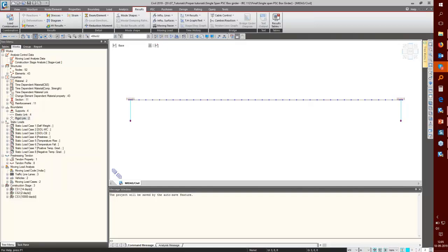Now the solution for this is, first we model a dummy model, or else we model the same thing without the friction coefficient, right? When we model it without the friction coefficient, we get the axial load in our bearings. Once we have obtained the axial load in the bearings, based on that axial load, we can model the friction coefficient stiffness.